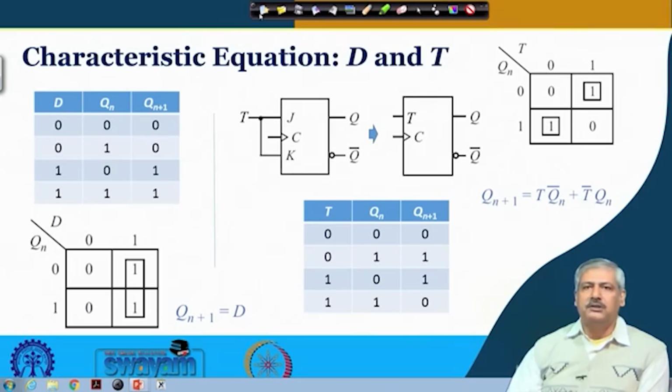Basically, if we try to visualize what would be the internal logic circuit of T flip-flop, then we refer to how JK flip-flop is made. Then we connect both the inputs J and K and tie them together. Remember, between SR and D we had an inverter; here there is no inverter. From SR to D we had put S as D and then R was D inverted, so there was a NOT gate. Here there is no such NOT gate, it is directly connected. So, it becomes a single input flip-flop.